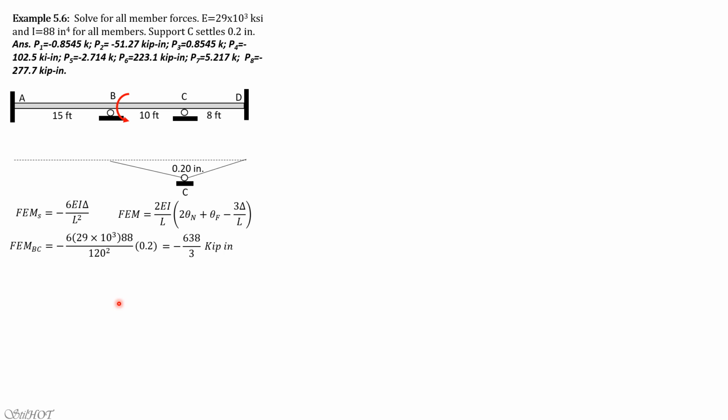For CB, on the other hand, that's the same, counterclockwise also. So the fixed force or reaction at B is upward. So fixed moment CB, on the other hand, because the rotation of the chord C to D is counterclockwise, then 0.2 is treated negative. The result is positive, and the positive moment means clockwise by slope deflection equation, as well as BC. It's also clockwise. They're the same.